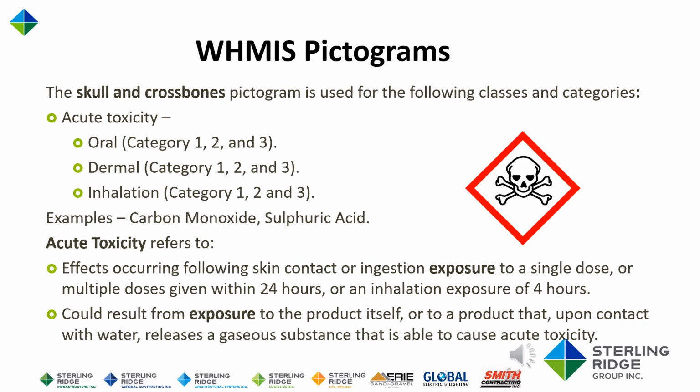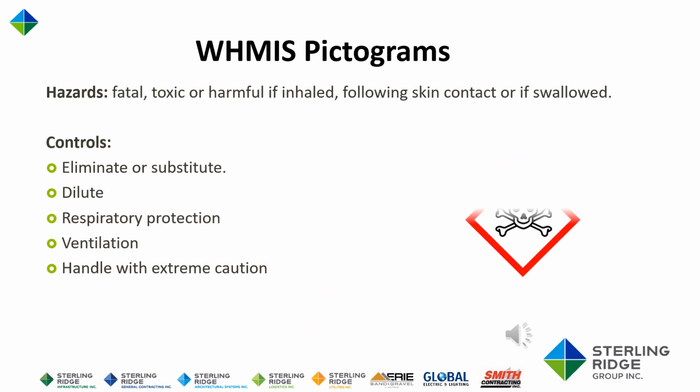Could result from exposure to the product itself or to a product that, upon contact with water, releases a gaseous substance that is able to cause acute toxicity. Hazards: fatal, toxic, or harmful if inhaled, following skin contact, or if swallowed. Controls: eliminate or substitute. Dilute. Respiratory protection. Ventilation. Handle with extreme caution.